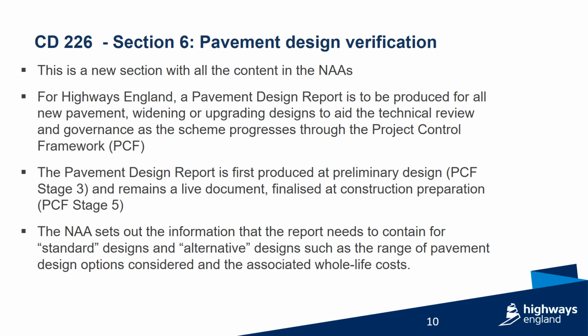Section 6. Pavement Design Verification. This is a new section with all the content in the National Application Annexes. For Highways England, a pavement design report is only required for all new pavement, widening or upgrading designs for schemes progressing through the project control framework. The purpose of the pavement design report is to aid the technical review and governance of major projects.